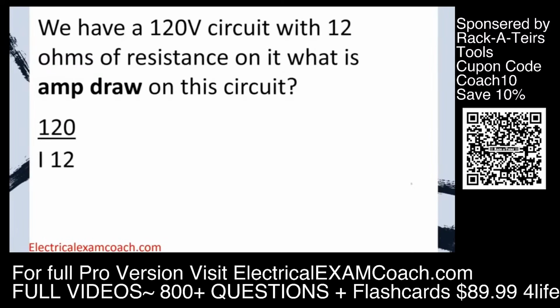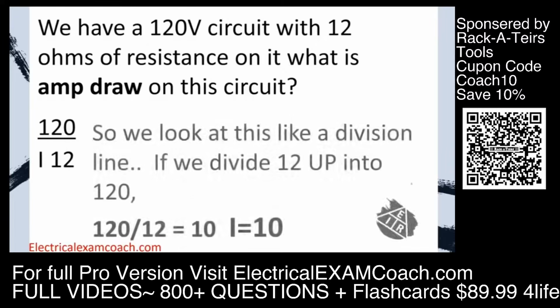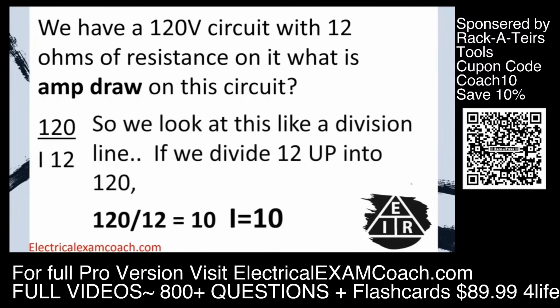Well, what I love about formulas is we just plug in what we know. We know we have 120 volts. We know that we have 12 ohms of resistance. And we're going to look at this like a division line. We just take 12 and divide up into 120. We set it up like this. 120 divided by 12 equals 10. That lets us know that there should be 10 amps of current on this circuit.